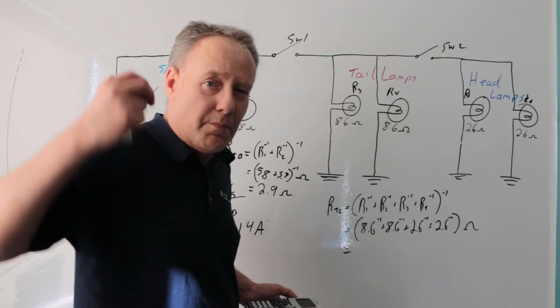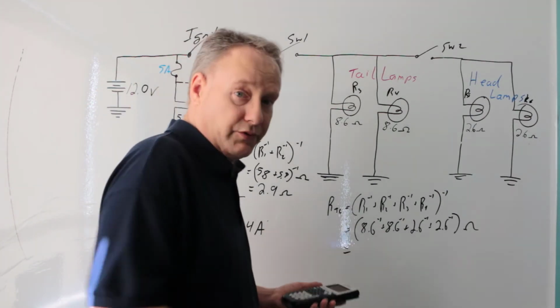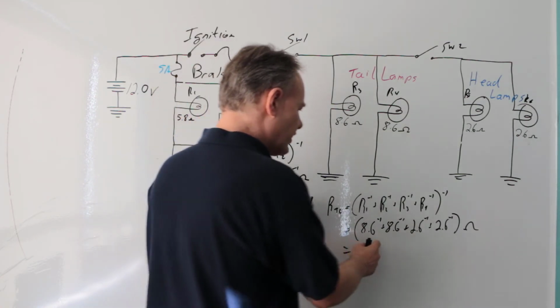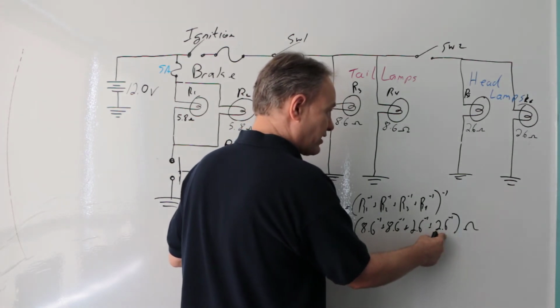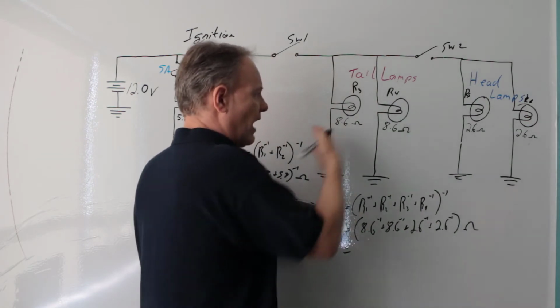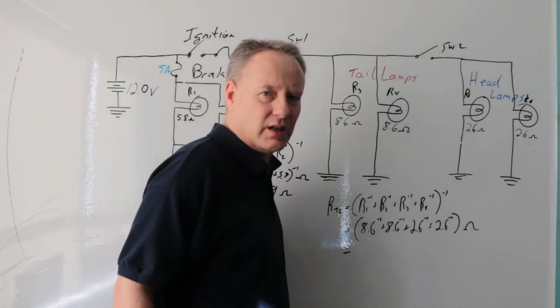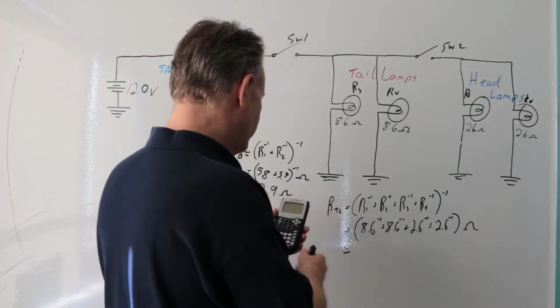It's 998 milliohms. Now I'm just going to check it again. Is that right? Well, it's okay to double check things. Wait a second. The total resistance is going to be definitely less than this. Actually, the resistance of this is 1.3. If I'm adding more resistance, it goes down. So yeah, maybe it is actually below 1 ohm. I'll do this again. It doesn't hurt to just do this again.